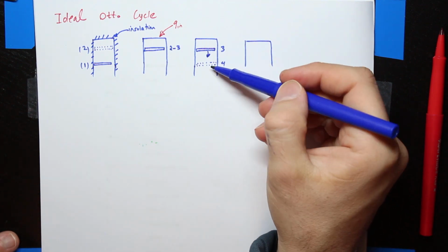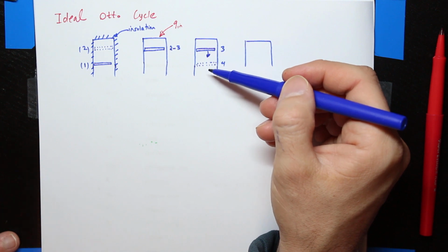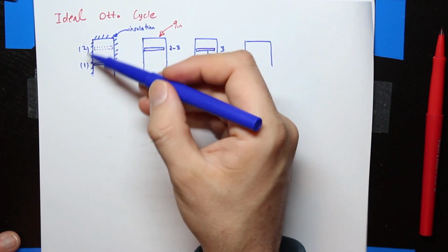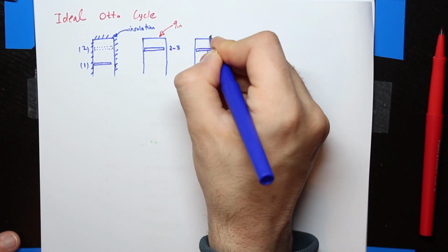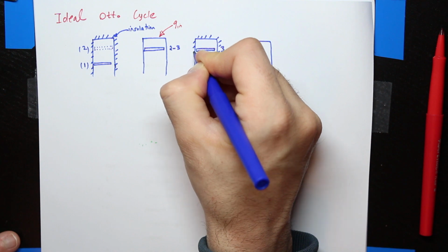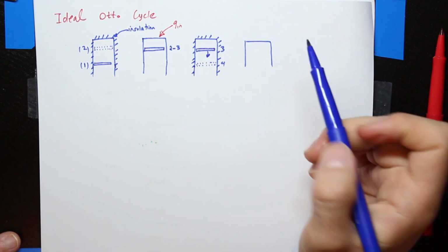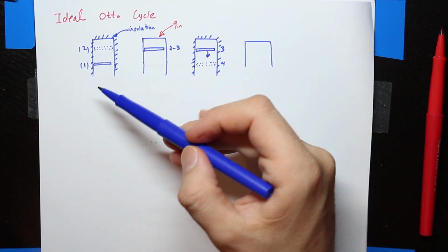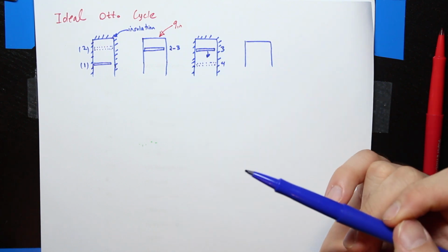There is mechanical boundary work happening here, which we can utilize in our vehicles. This schematic is similar to the first one: there is no heat transfer from the cylinder to the surrounding or vice versa, which means we have insulation around the cylinder. So insulation here, no insulation in the previous one.